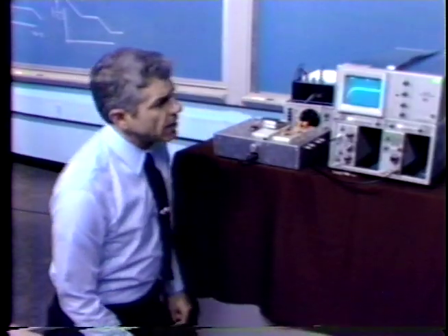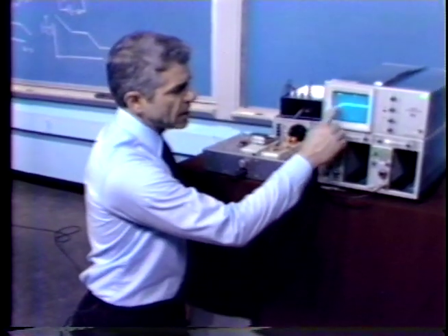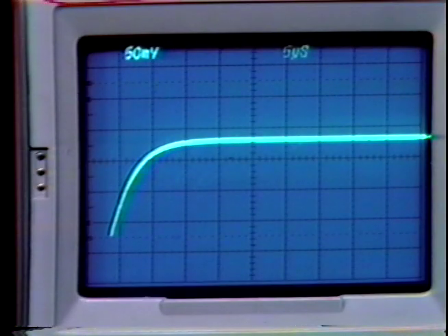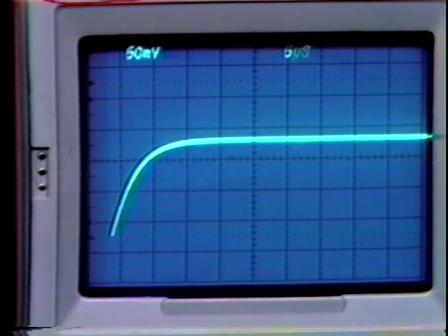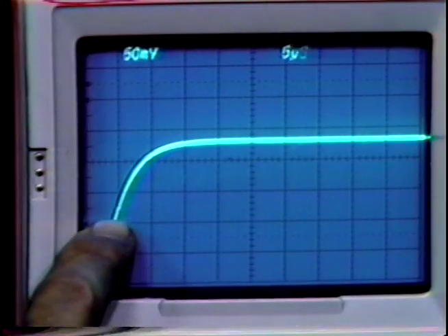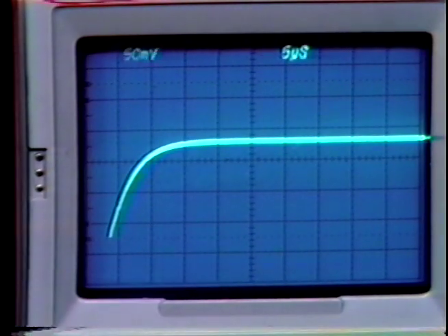And the result of that, of course, is to give us effectively an exponential kind of response. We'd expect when our loop is rolling off as 1 over S, we have a first order system. We've chosen numbers so the crossover in the loop occurs well below any additional phase shifts associated with the amplifier itself. So we get a response that looks very, very nearly first order.